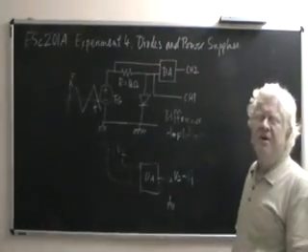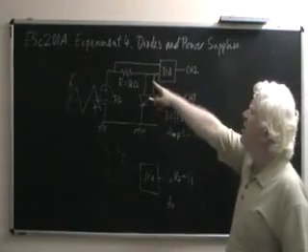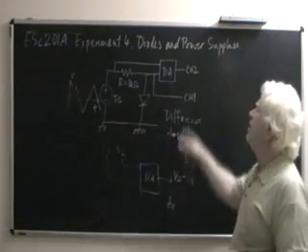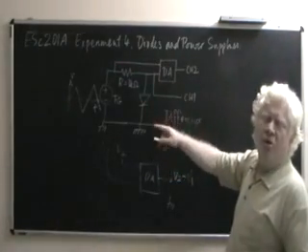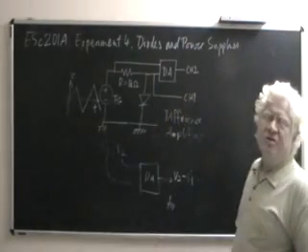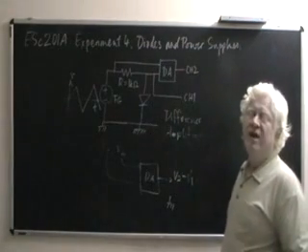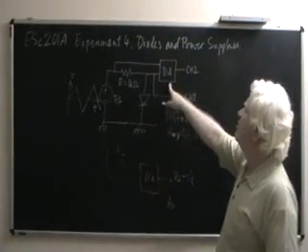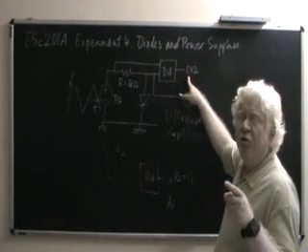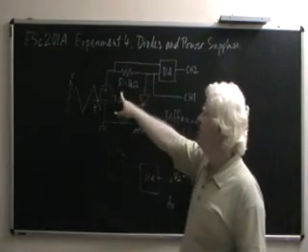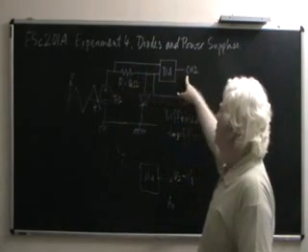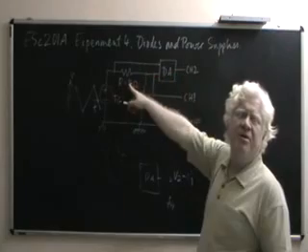That is possible, but if we did that, just the measurement of the current or the voltage proportional to the current would consume both the channels, and we would require a third channel, which means a new scope altogether, because this scope has only two channels, to measure the voltage of the diode. Thus, to save on oscilloscopes, we use a difference amplifier, and the difference amplifier gives you an output proportional to the current. To work out the constant of proportionality, look at this resistor. This resistor we have used is 1 kilo ohm. So if it gives you 1 volt here, that means the current is 1 milliampere.